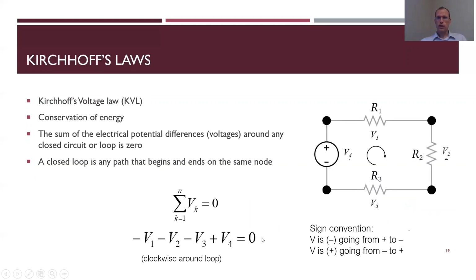The voltage law is essentially conservation of energy. So whatever happens to the voltage has to come back to 0 essentially. So again, I'm treating my negative side as the ground as 0. I have some positive voltage, and that number, whatever it is, say it's 12 volts, has to be doing something. So this 12 volts is going to be going through, in this case, 3 resistors, resistor 1, resistor 2, and resistor 3.